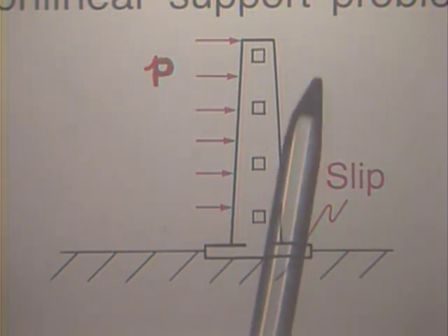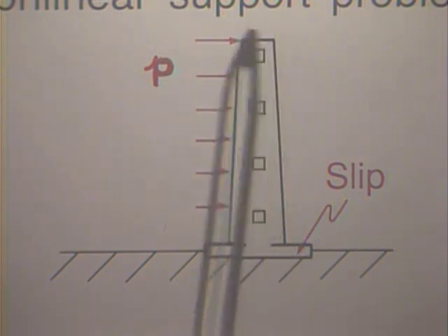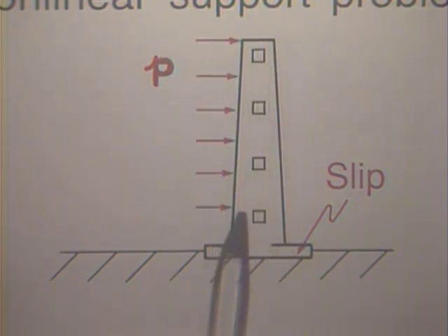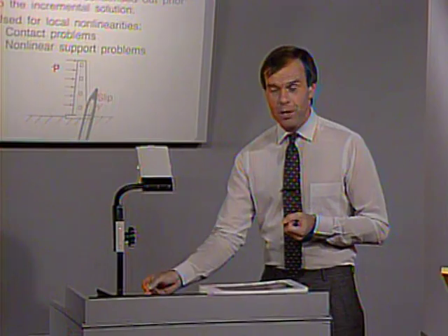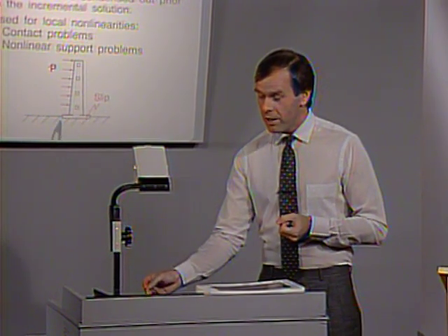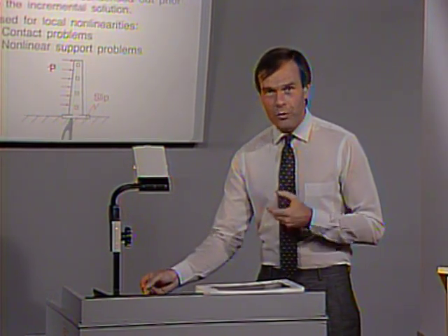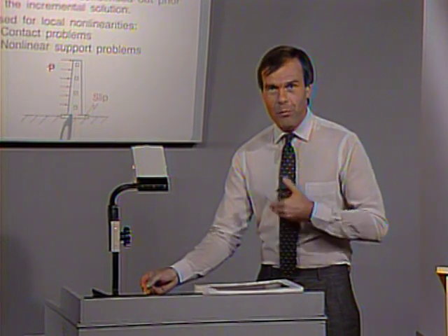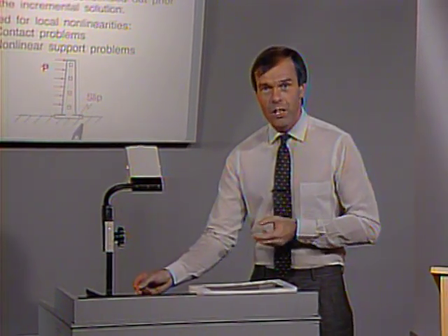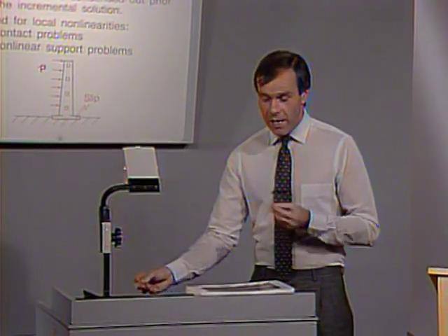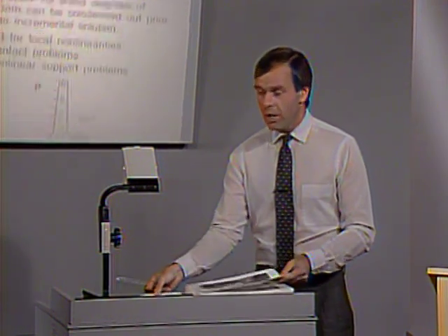This typically would mean that we have a large number of linear degrees of freedom that we can deal with very effectively using the substructuring approach. The nonlinear degrees of freedom here, of course, require iteration and updating of matrices, and those we deal with in the usual way. Let me show you in more detail what I mean here.